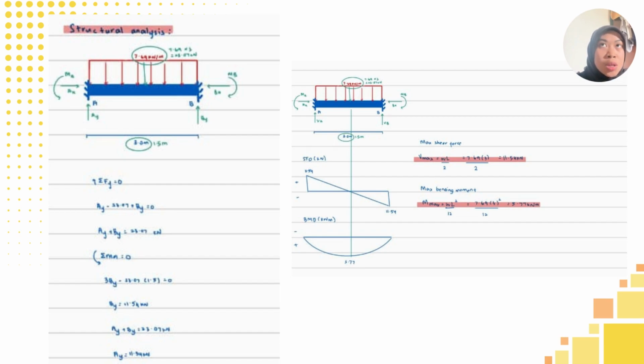That helps me to identify the maximum shear force, regions of positive and negative shear, and the critical section that may govern shear design. And as for the BMD, I use the shear force results for the bending moment at key sections along the beam was calculated.